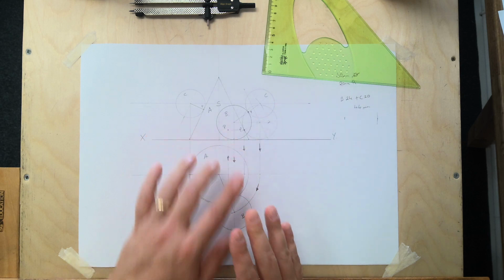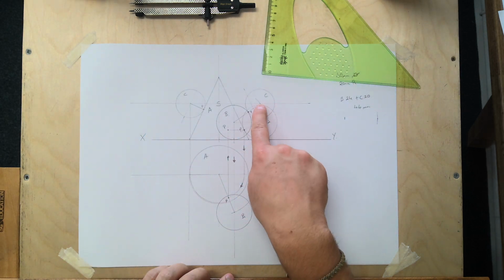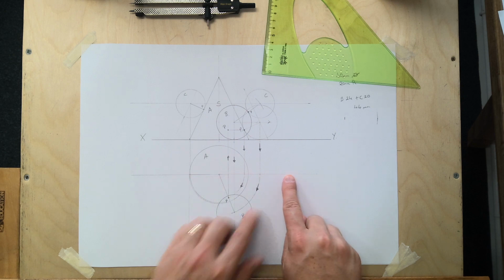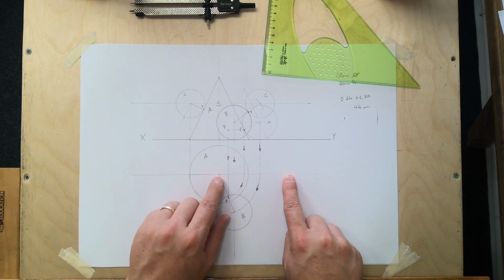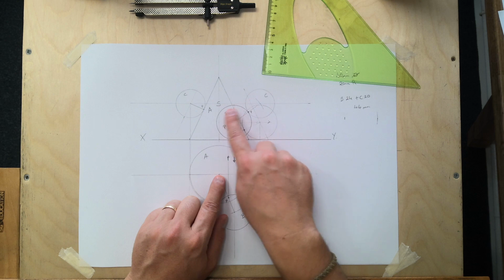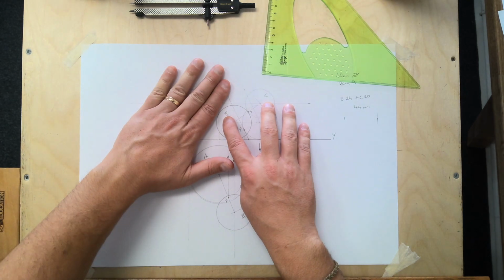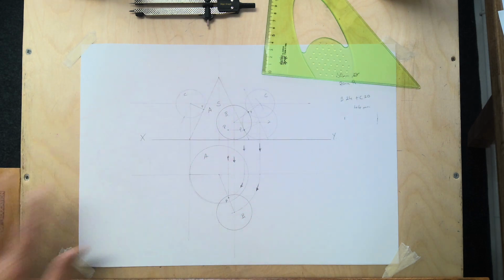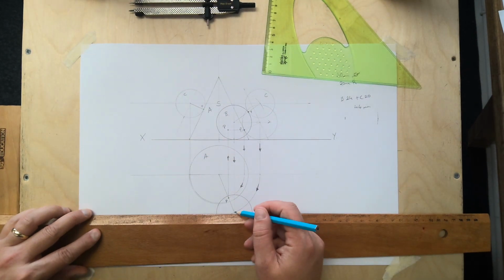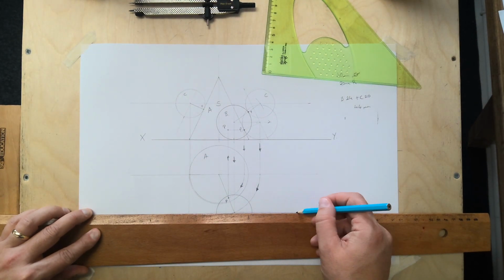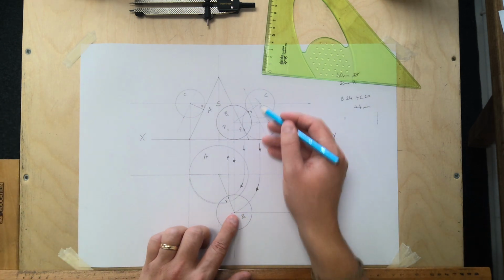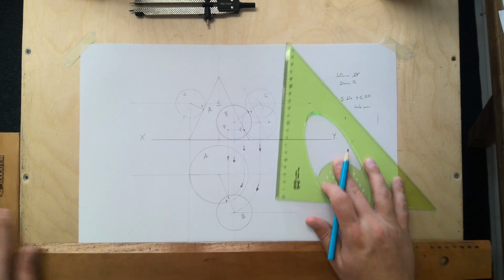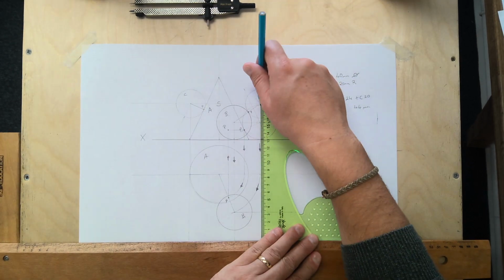So we've made them in contact with one another. Now you have to just remember, to try not to make the mistake this time. When we bring down the center point, we don't stop here, because this would be the horizontal line that we're using for the cone. We're now working with B and C, pretending A doesn't exist, B to C. So we need to bring C down to hit off A down below. So that's where some people can mess up, alright? So light line out, because we're doing an edge view, so therefore they have to connect here, alright? Bring down our center point.